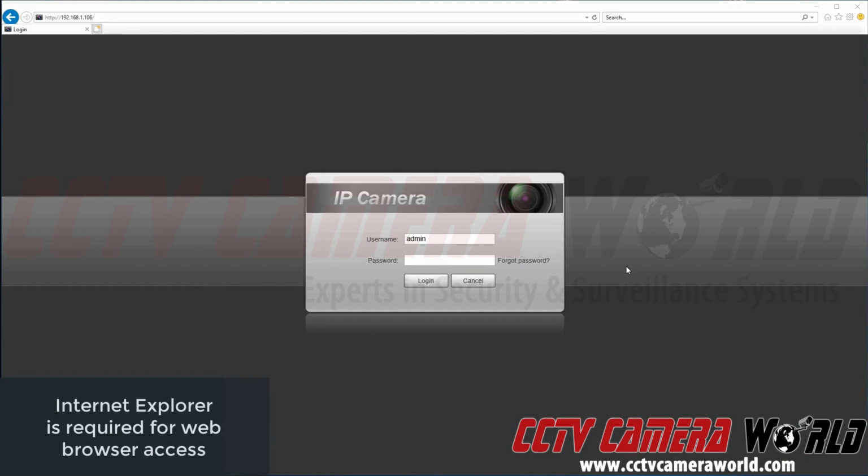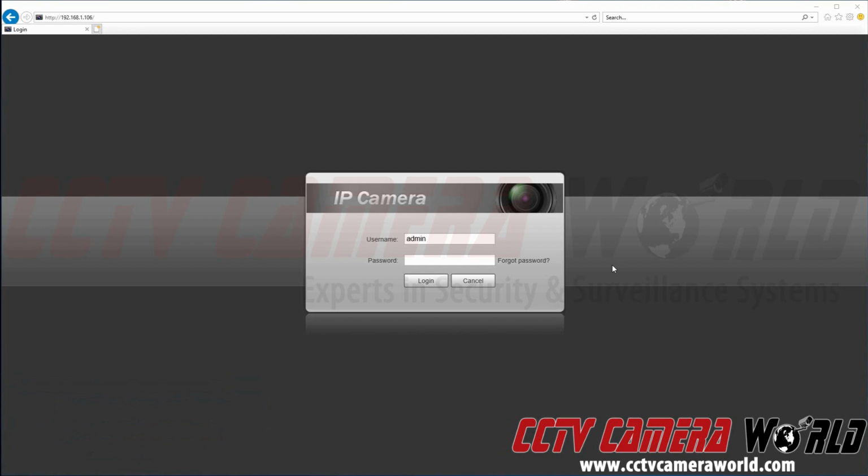In this video, I'm going to show you some of the best practices for using an IP camera that has a line-in or a built-in microphone. Here we already have the camera pulled up. We're at an address of 192.168.1.106. Most of our cameras ship with a default address of 192.168.1.108. So here we already got it pulled up.